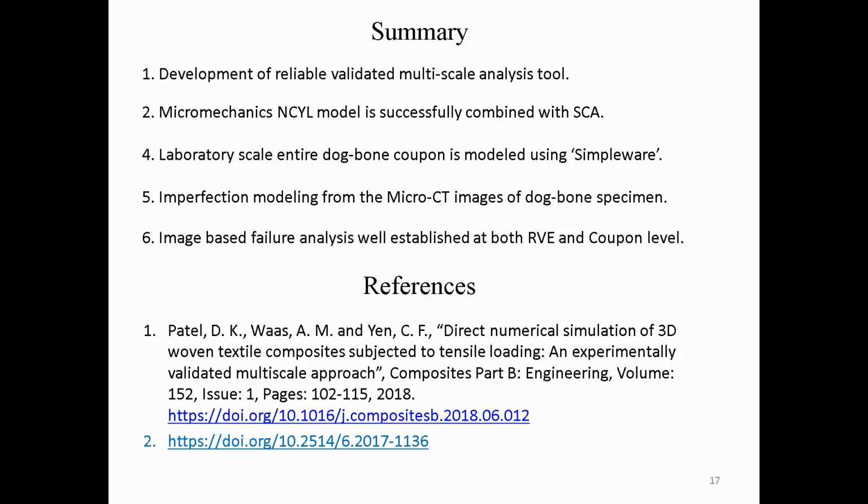So we had a multi-scale model, which is NSIL plus near crack, but the CAD model is totally brought in from Simpleware, which is purely micro-CT based. The advantage of this, and the whole work, was to demonstrate how the image based model includes every imperfection: all the porosity, all the curvature, all the imperfections inbuilt in the fiber tows, all the waviness, which is included in the analysis. So there are no assumptions in this analysis, and this is for the whole coupon.